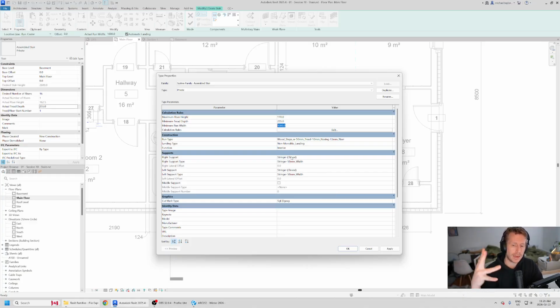So there's a lot of settings inside of this that we need to be mindful of when we're building our stair. For us, you could use these parameters for now, and I think that this is just going to help us out. Maximum riser height, this can be 200. That looks good. Run type. Don't touch any of this for now. In future iterations, we could totally mess with some of these, but these are literally every single piece of the steps. If I hover over here, is it going to give me a little tooltip? Maybe it will. Built-in parameter.